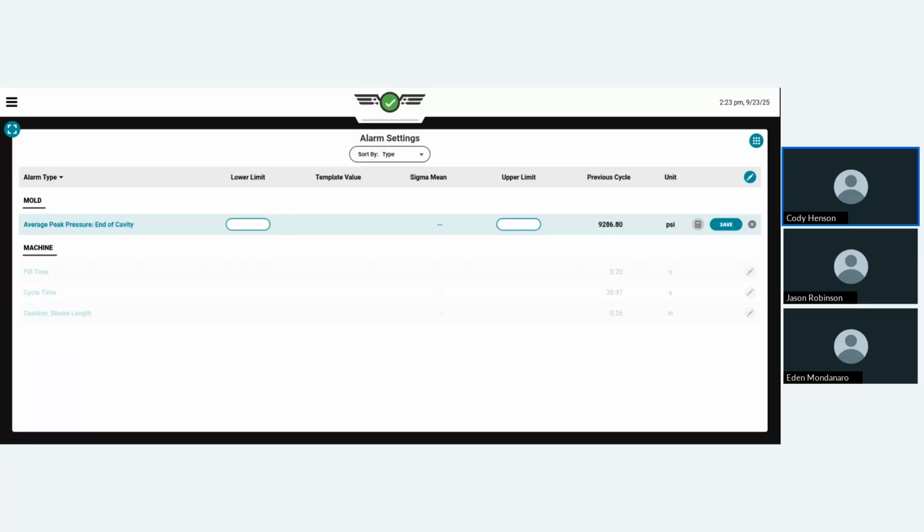And then set that lower limit just above that, with the idea being that if it's going to kick it out before it's short, it's definitely going to kick it out when it's short, right? So kicking out suspect parts, not just waiting until you have a large chunk of the part missing. We want to have some boundary before that.